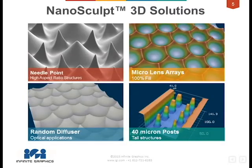Here we have some examples of the NanoSculpt 3D solutions being applied to different structures. In the upper left-hand corner, you can see we have a cone and needlepoint design that is used in a medical application. To the right there, we have micro lens arrays. And one of the intriguing capabilities of NanoSculpt is 100% fill on those lenses. Down in the lower left, a random diffuser, and again you can see that the shapes are indeed random, which is difficult to do, but the NanoSculpt solution set can be used to create these kind of structures. And lastly, we have various kinds of tall 40 micron posts with various aspect ratios.